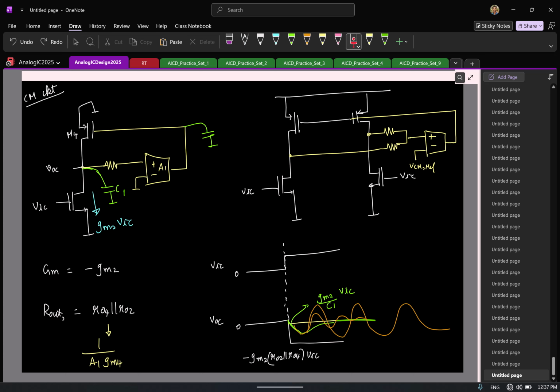In presence of delays in the loop, even though the CMFB is eventually trying to suppress the changes in the output common mode, because finally it is making the output common mode equal to this reference value, so small signal change should be 0 ideally. Although it's trying to do it in steady state, in transients you cannot guarantee it. You can have large common mode variations.